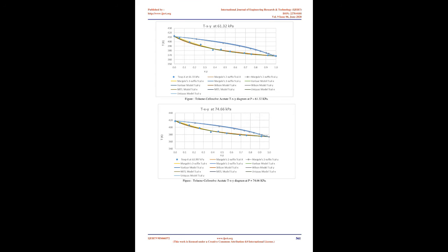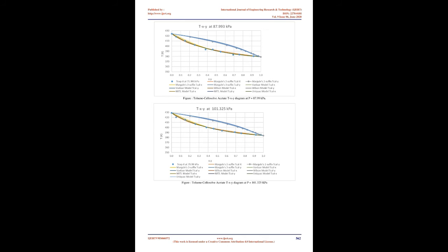Wilson model. Vapor pressure was calculated using the Antoine equation. Parameters were regressed using the above-mentioned models for all the binary mixture data, and using them, bubble T, or the bubble temperature, was estimated. Experimental PTX data are modeled to find vapor phase composition using GE-based models with regressed parameters. Activity coefficient model parameters are regressed using experimental PTX data. Then experimental PTX data are modeled to find vapor phase composition, and the vapor phase composition and temperature are compared with the calculated bubble T data.